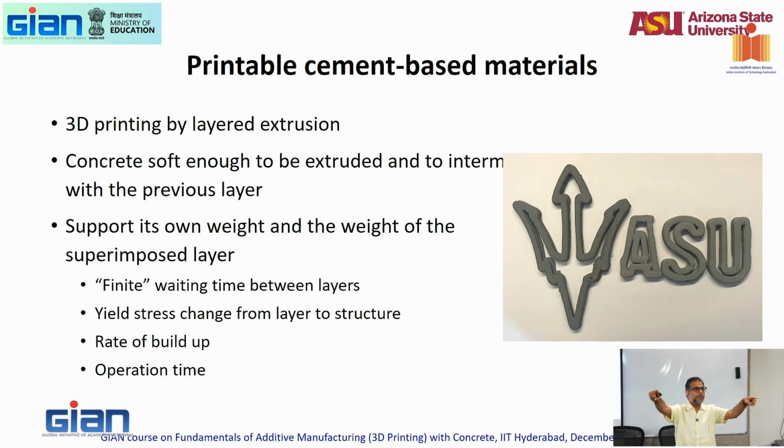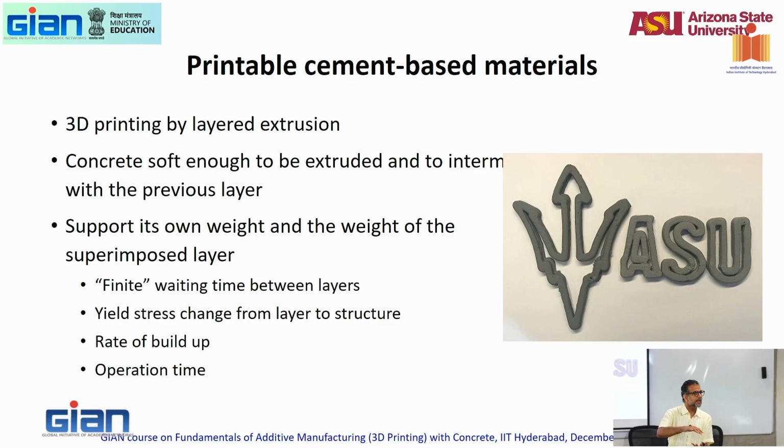So if I have to build a rectangular shape, I need to know how big of a perimeter I have and how fast I can print, so that by the time I come back to the original shape, original location, a certain amount of time has passed by which the initial concrete that I have laid has some strength to carry the next layer. You see that? So your printing path, how do you adjust the printing path?